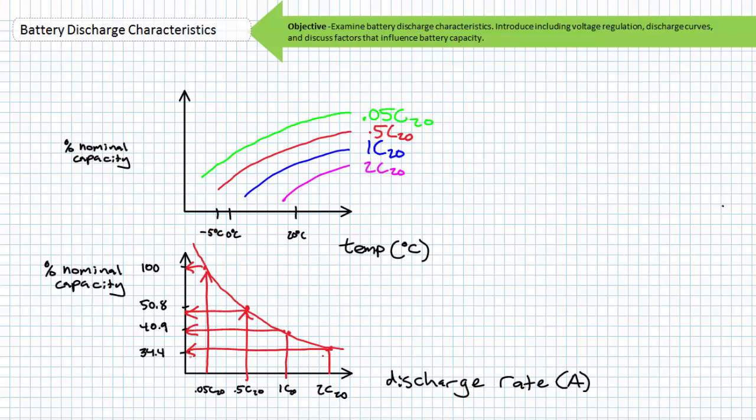Other observations can fill out the graph and a curve can be approximated. This allows a user to quickly estimate the effects of discharge rate on capacity. The top graph, in combination with temperature effect, tells 2 stories at once. Not only does temperature affect capacity, discharge rate also does so, and by tracing the appropriate discharge curve, one can estimate capacity at the appropriate temperature.